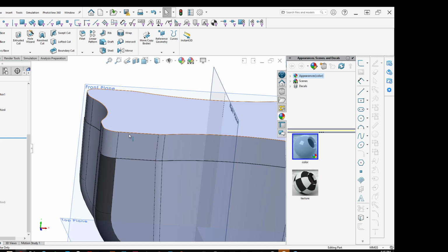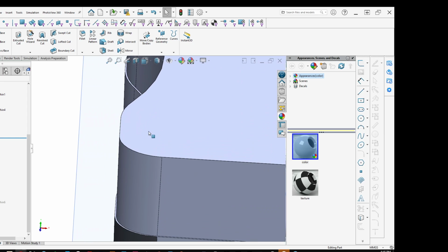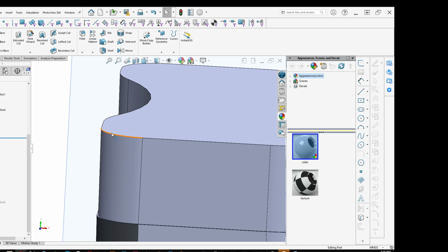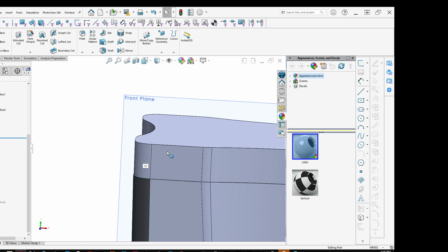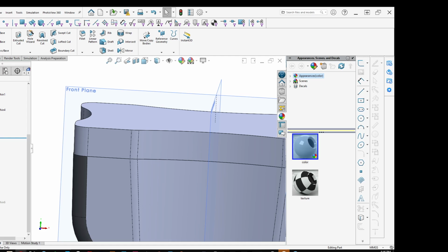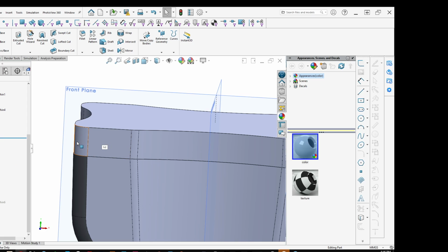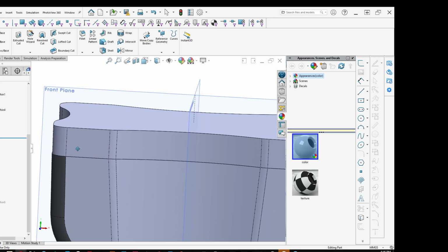So, since you built the part up here, what you have to do now, in order to get the draft on this the way you want it, you would need to come back and figure out how much you offset this in and then draft it down. Does that make sense? Yeah, I know what you mean. Yeah, you could just delete that extrude and convert entities down and rebuild it from the bottom, couldn't you? Yeah, you can. You want to plan ahead because that would be a fix, and you're going to make your model more complicated.